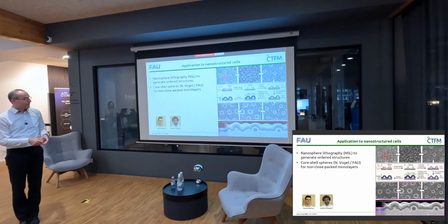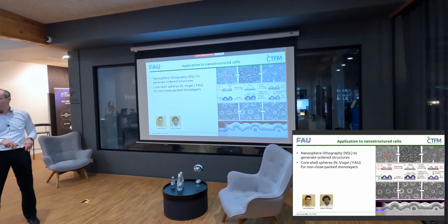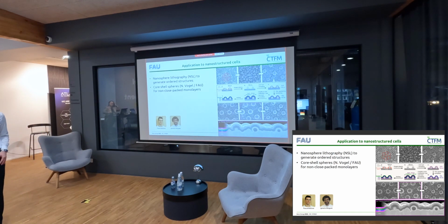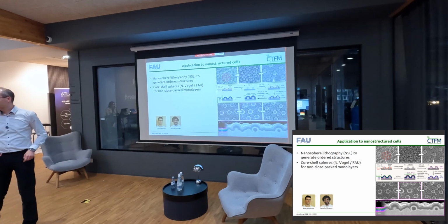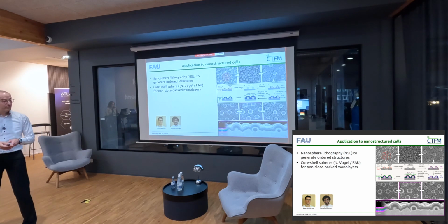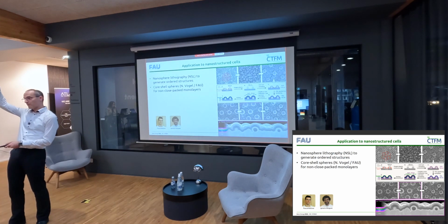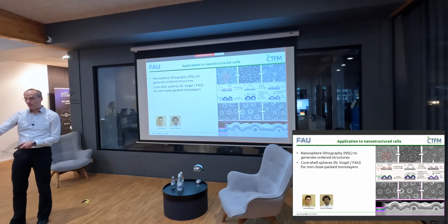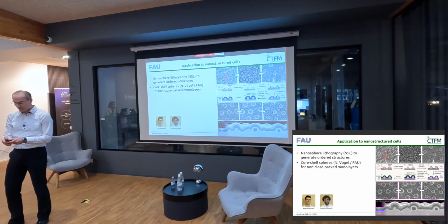This is a structure that we've made with a self-assembled monolayer of spheres that can now be coated super nicely with all the layers using ALD, which would not be possible otherwise, and which have a distance of 700 nanometers. Perhaps you remember that antimony sulfide starts absorbing at 750 nanometers or so. So 700 nanometers is exactly in the red where absorption is less strong. But if we scatter that light, the light beam, instead of just passing through once, will get scattered and be absorbed more efficiently.